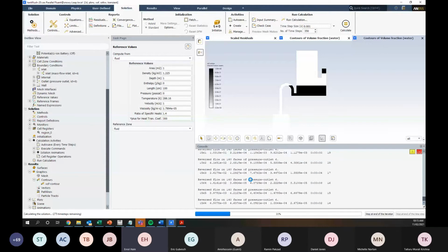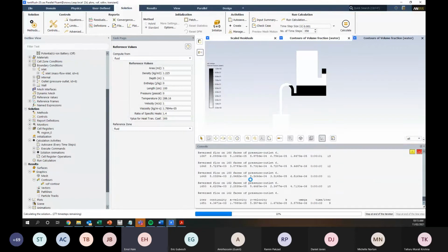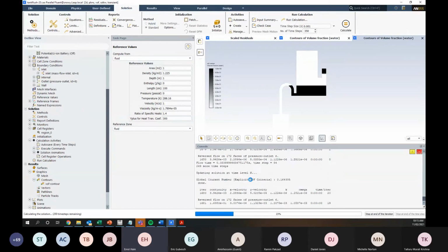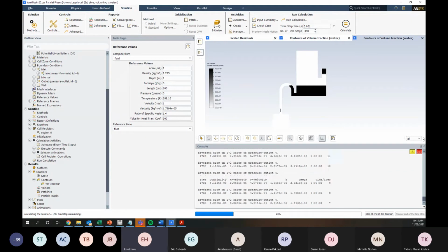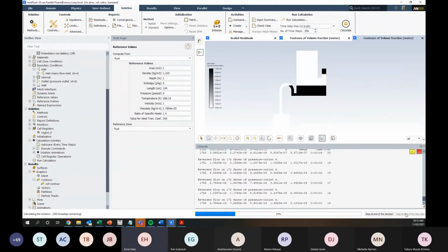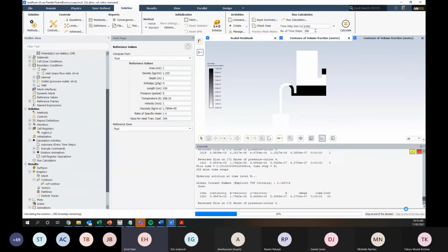You need to be going into LES models and things like that. Is there a way to confine the two phases with a non-slip surface? You can have separate cell zones, so multiple different cell zone areas, and different fluids in each. Yes.